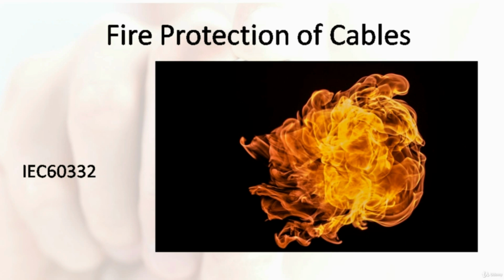This space is usually located between the structural and suspended ceiling, as well as under the raised floor. Now, if there's any place where I would recommend extra fire protected cables, you should install them in these areas, as these are what we would consider high risk areas for catching fire and spreading fire.